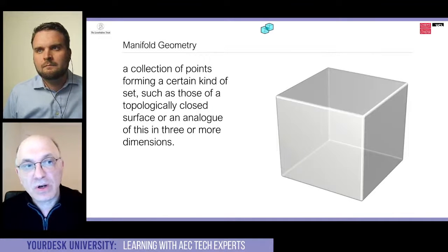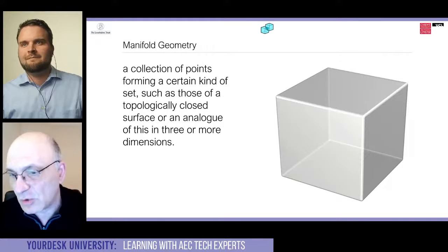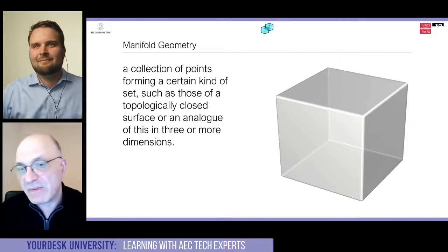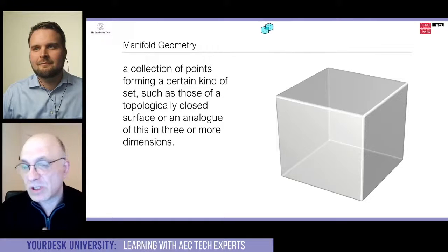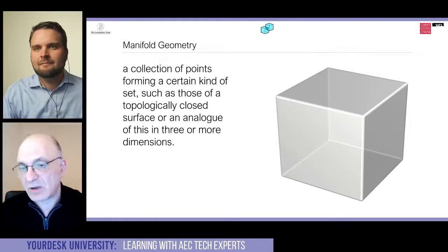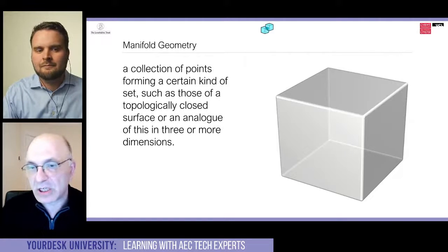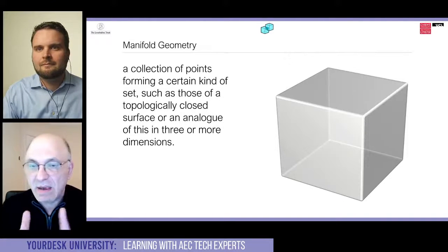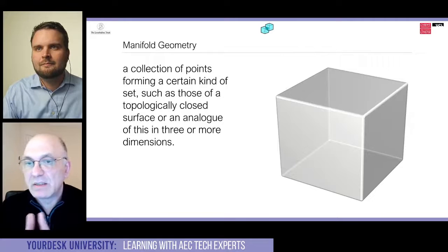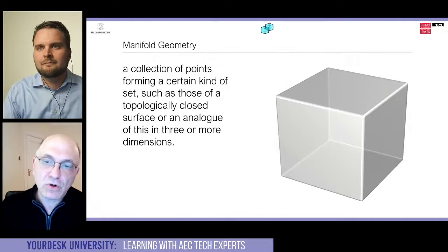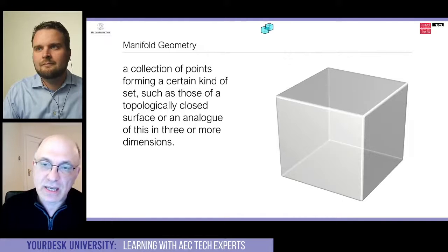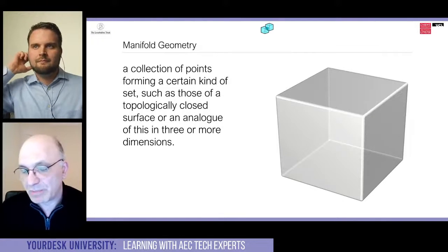So you've heard me talk about manifold and non-manifold. What does that mean? That always trips people up. It's very, very simple. A manifold geometry, which is mostly all your CAD systems that you are using right now, are based on manifold geometry or solid representation of objects. Basically, every point on the surface divides the world into 2 states. Either you are outside in the void or you're inside the solid of the object. And that's why it's actually called a 2-manifold, and that's called a manifold for short.